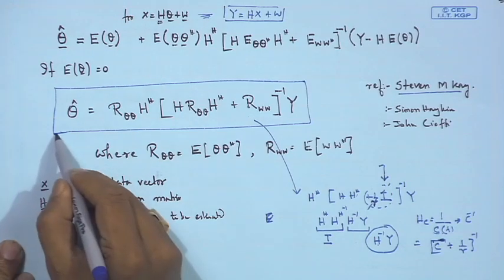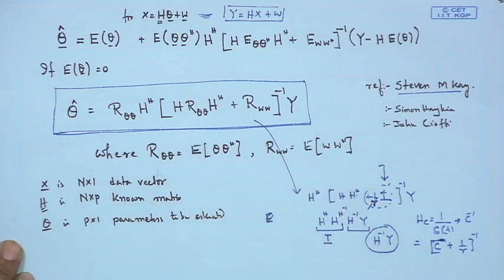So, we usually go for this kind of an MMSE receiver. However, a side note for those who are very keen with these kind of receivers, these kind of receivers generally do have a bias. So, one may be required to remove the bias, but at very high SNRs, the performance of this receiver is comparable with that of zero forcing, when inversion of zero forcing is not a problem. If inversion of zero forcing receiver is a problem, then they do not compare at all, because in case of zero forcing, the matrix does not get inverted.